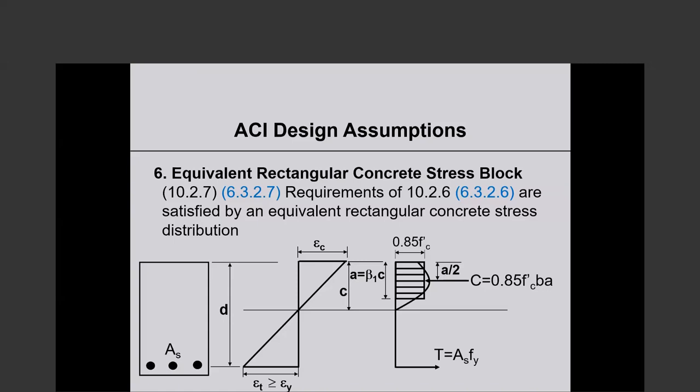And that is because of something I said yesterday you may or may not have caught on. As long as it is an under-reinforced beam, the behavior is determined almost entirely by the reinforcement properties. The concrete plays a very modest role, if any. So what you postulate to be the stress-strain relationship of concrete does not really matter.